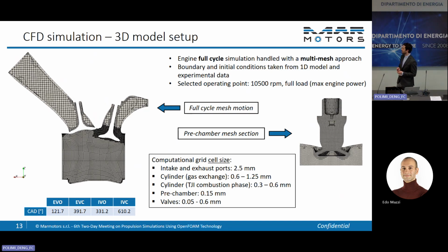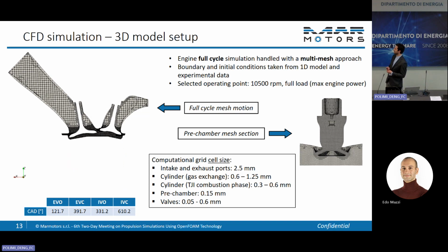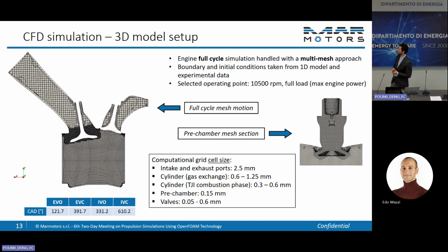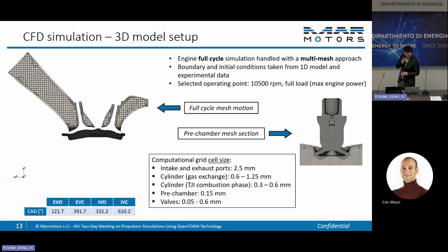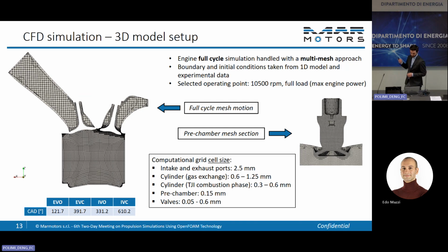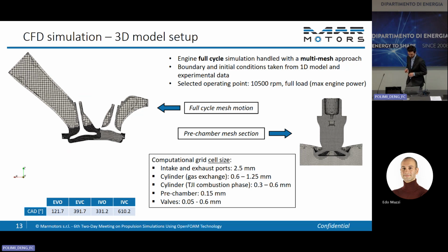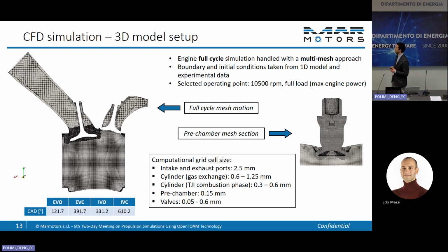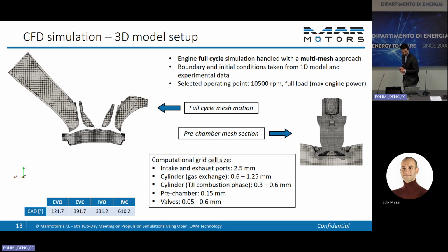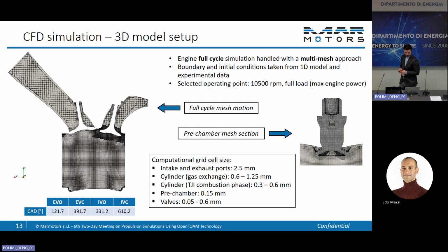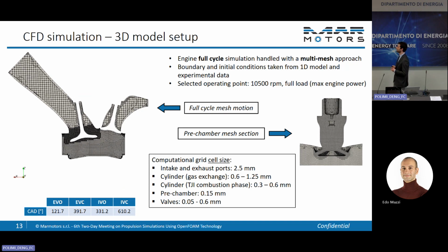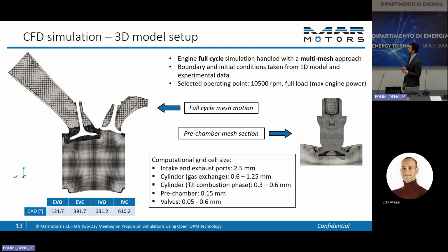This is the work that we did in strict collaboration with the Politecnico di Milano, in terms of simulation and validation of the model with this engine. So a full cycle simulation was performed, and we chose the peak power regime at full load. And as you see, in terms of mesh, there is grid refinement around the valves and inside the prechamber in order to better capture the fluid motion.